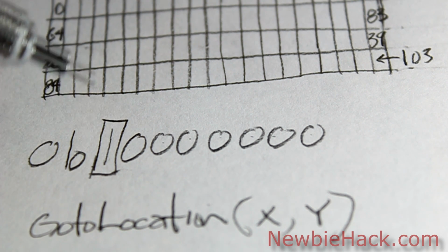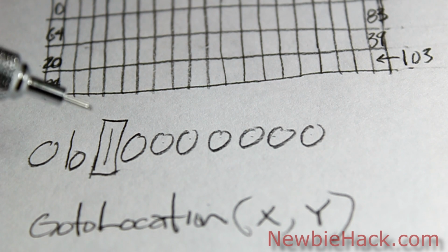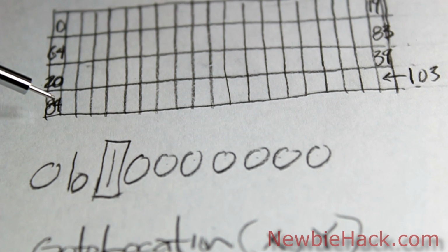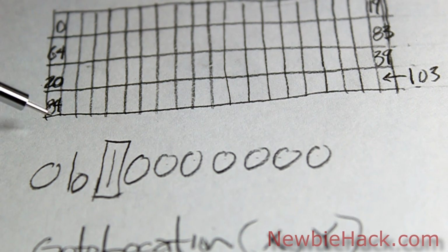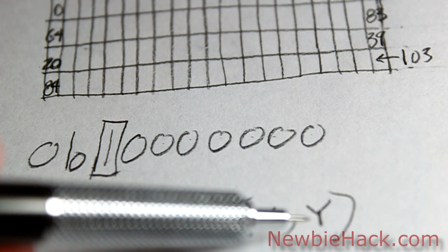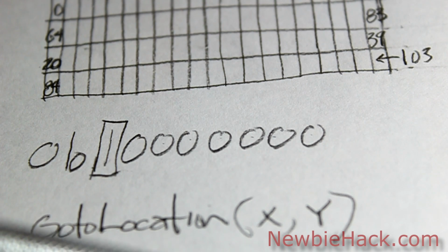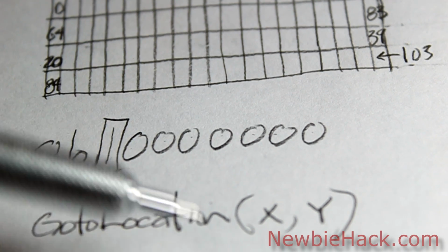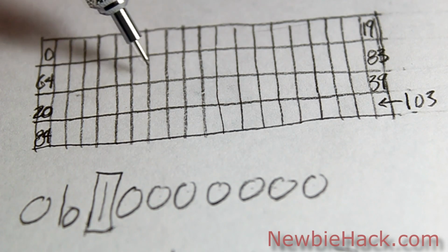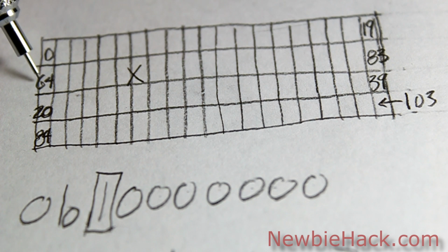We can store this in an array, or we can store this in separate variables, or we can even create a define statement at the beginning of our program that has these numbers, and we can change these depending on our LCD that we use. If we store it into an array, it'll be easier to use it with a Y location. So the array could be an array of 4 different positions, and we just add X to it, because if we say like 64 and we want the location to be here, we would just add this number of positions to 64.